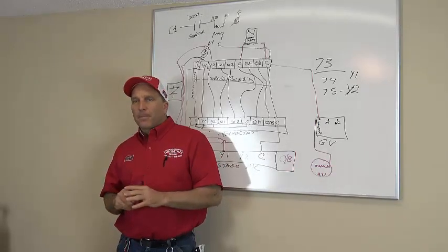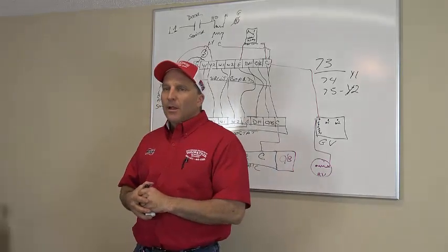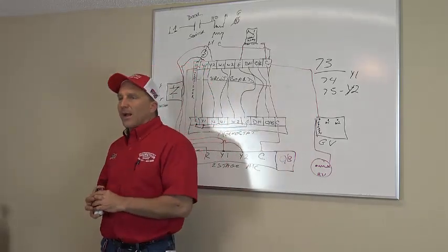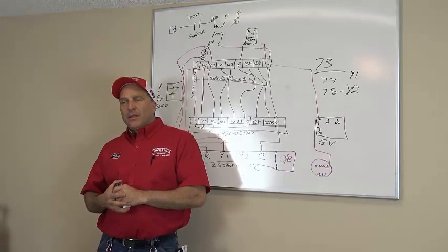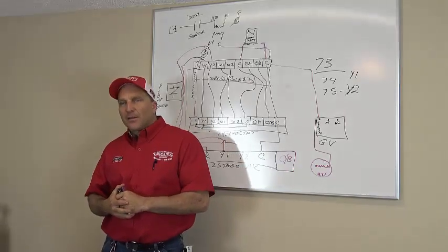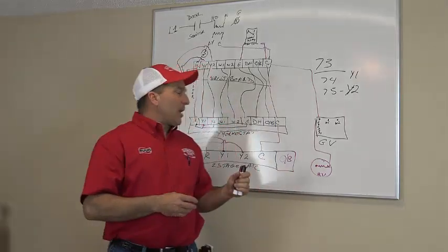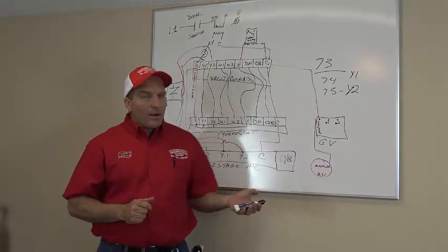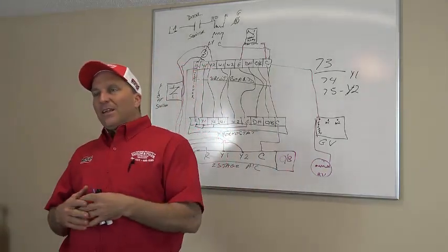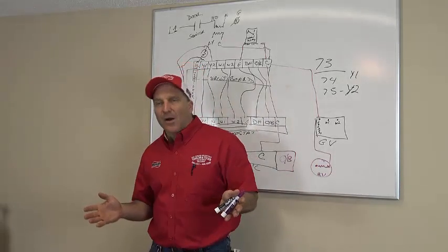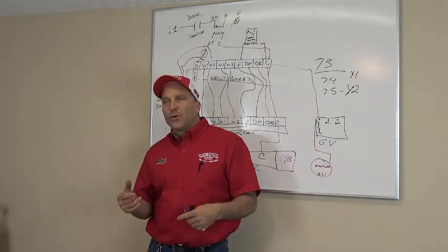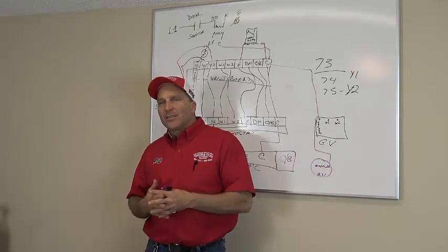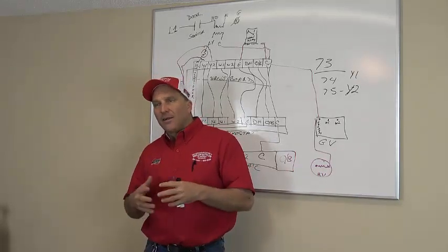The compressor starts going faster, or the compressor does not go faster. There's a solenoid valve inside the compressor. It is a relief valve inside the compressor that when you energize Y1, then you are only getting 70% capacity out of that system. When you energize Y2, it actually will energize the solenoid valve inside that compressor.